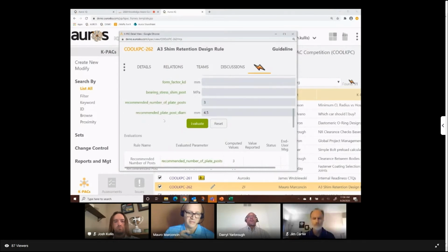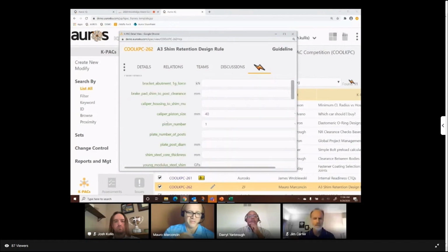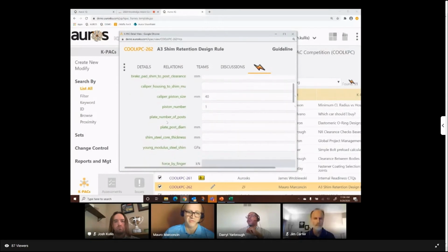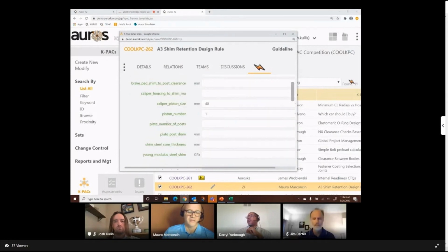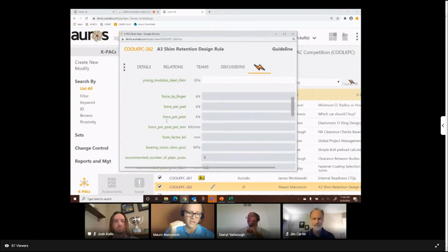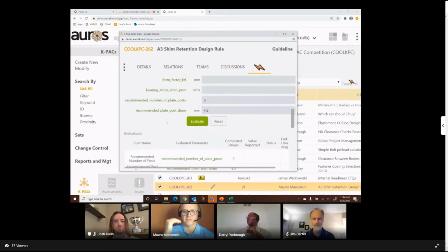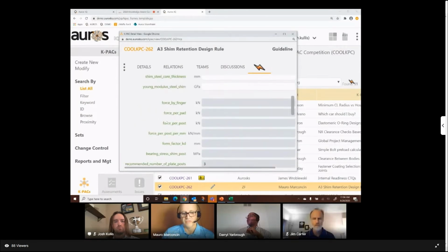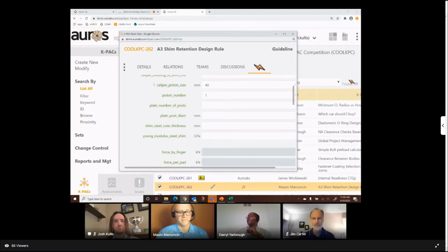So with these numbers, which are some numbers that I just modified for this presentation, the user is supposed to go back into the top of the value table, put those numbers in, put the rest of the information, force level, other attributes, and it's going to calculate the stress level for this component. If the stress level is okay, it's going to show as green. If not, it's going to show as red and recommended modifications to the inputs to go through. So I believe that's what I had, Josh. Thanks, everyone.